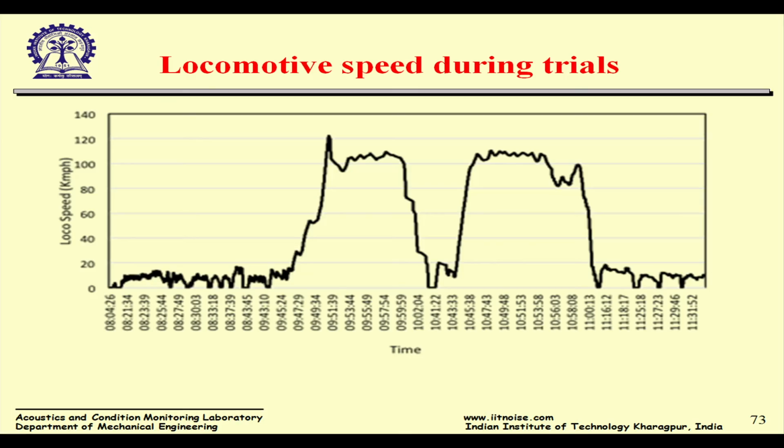So this is just to briefly give you some of the activities which you do in terms of some case studies, and I could go for hours on case studies, but just to give you an idea. So anywhere you have to do noise control, please understand the basics, measure correctly, number one, know the limits of your instrumentation, and then identify the source, the path, know the technology available, apply them, evaluate them, and that's it. It's that simple. It's no rocket science, let me tell you. Noise control is not rocket science. Okay, it's very easy provided you follow these procedures.